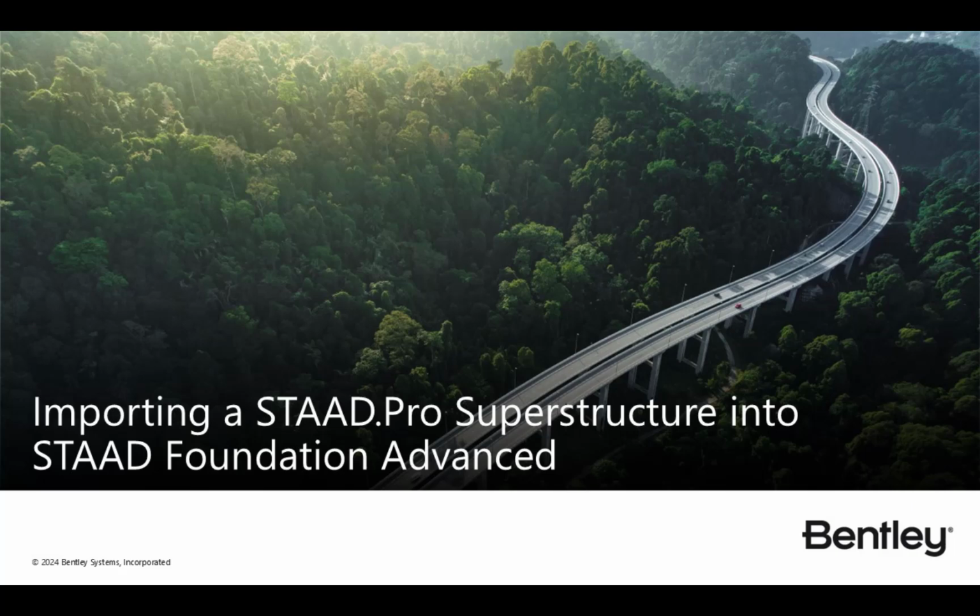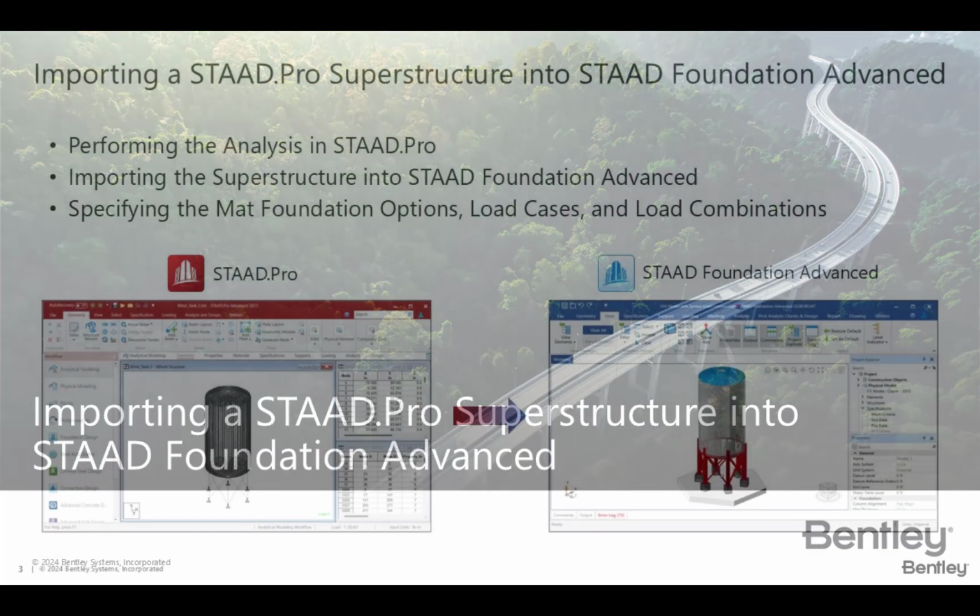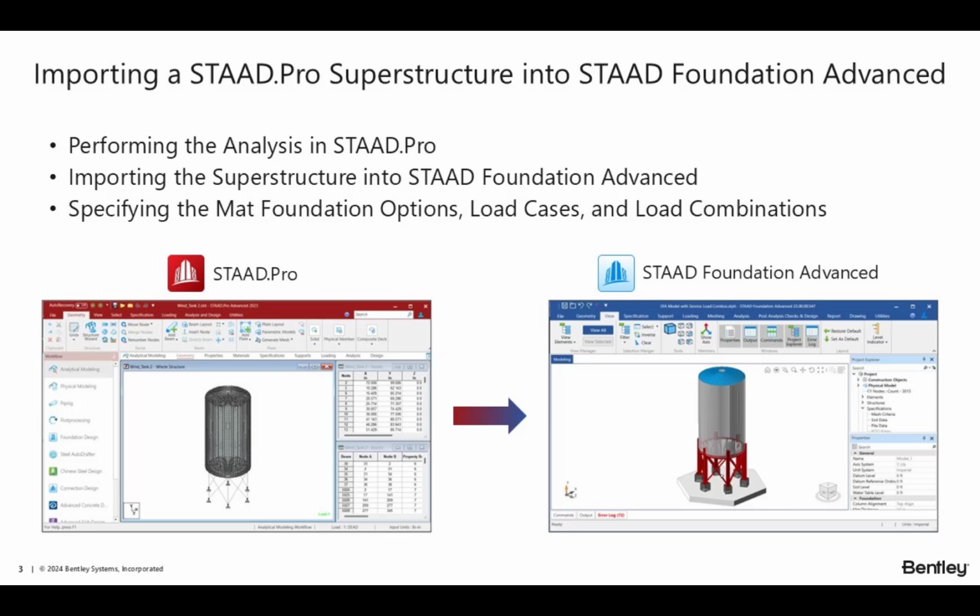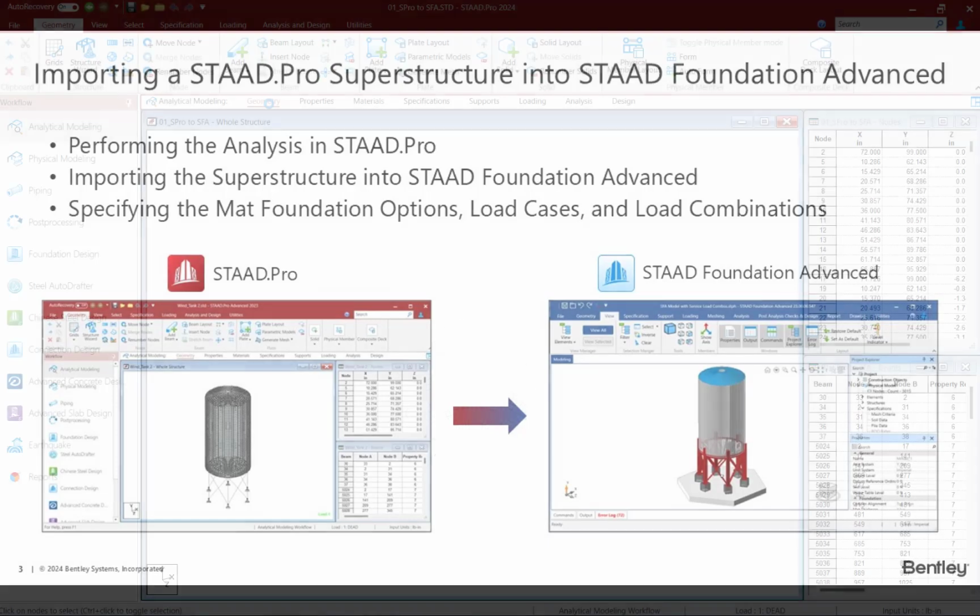Welcome to the Bentley Systems training course, where you will learn how to import a STAAD.Pro Superstructure into STAAD Foundation Advanced in preparation for designing a mat foundation below the supported columns. This workflow will include the following steps: performing the analysis in STAAD.Pro, importing the superstructure into STAAD Foundation Advanced, and specifying the mat foundation options, load cases, and load combinations.